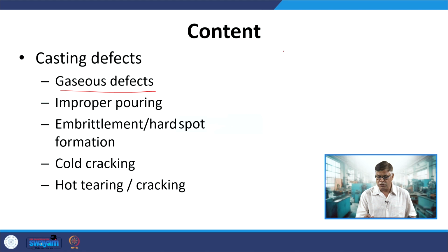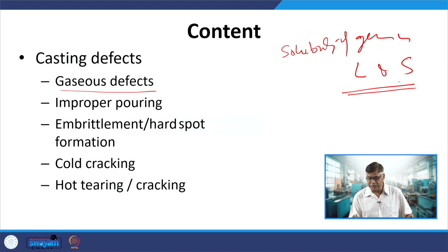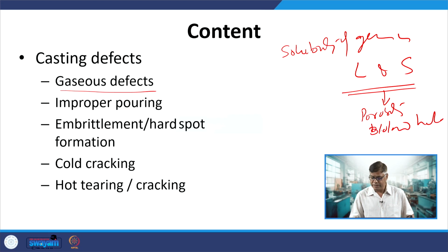So, the major issues include the gaseous defects. One is the solubility of gases in liquid and solid state. If this solubility difference is too much, then it promotes gaseous defects like porosity and blowholes.